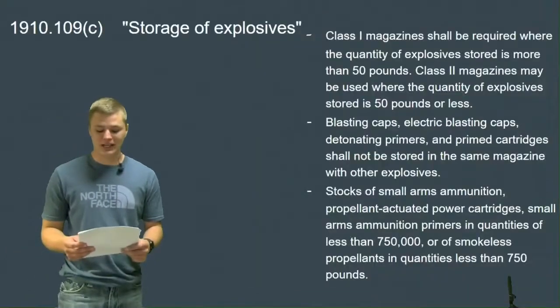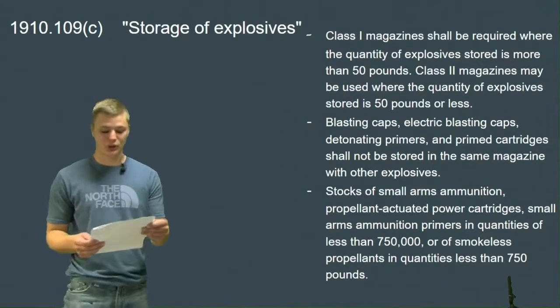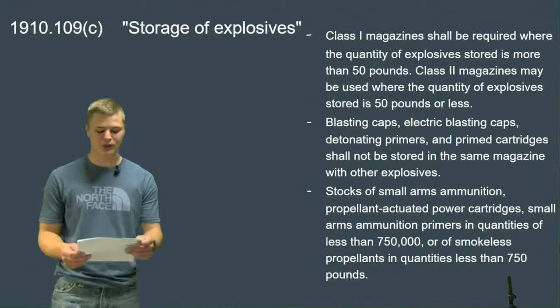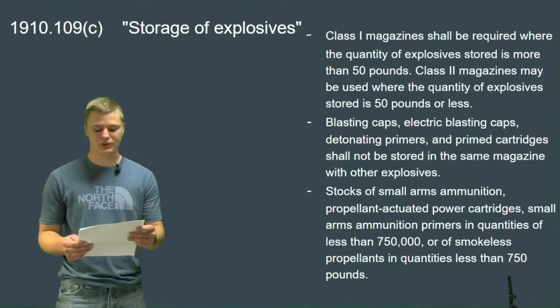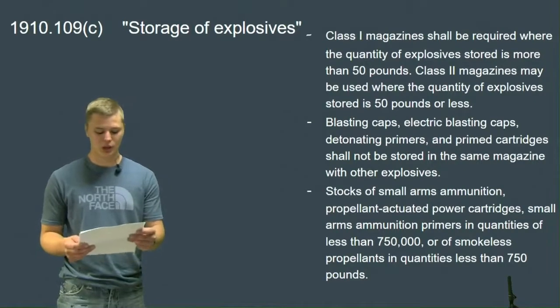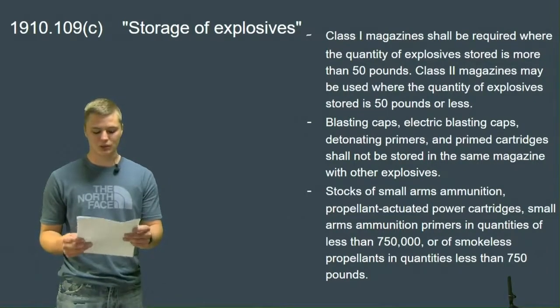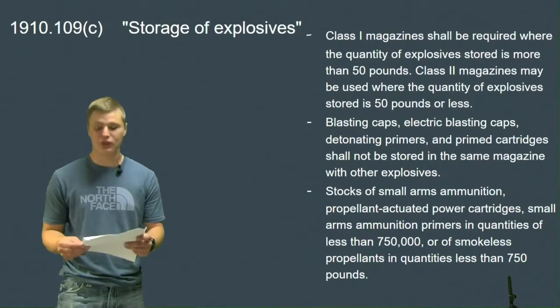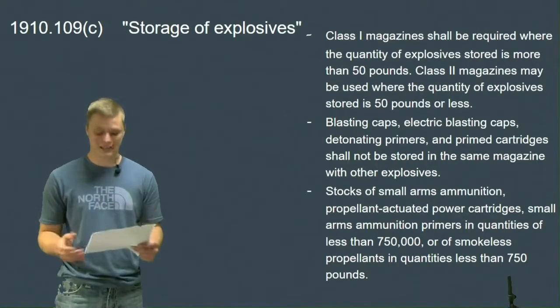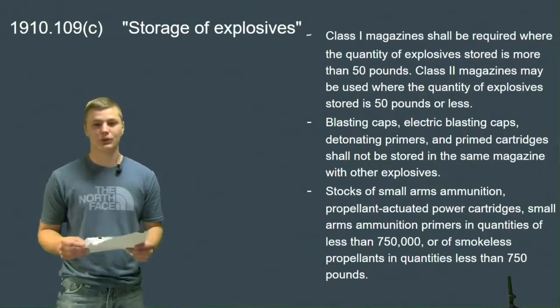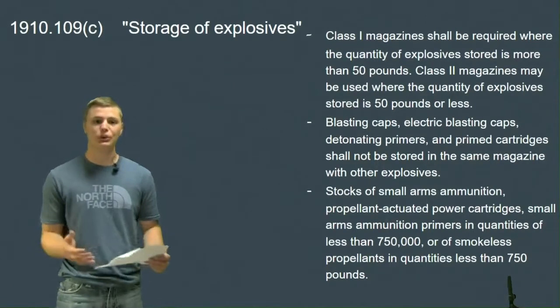Now that you know about the blasting and explosive materials you are going to be dealing with, it is very important that you know how to store them. Once again, these materials have the potential to cause harm to you and others around you if not stored correctly. Just to clarify, when I say the word magazine, it is referring to a building in which we will be storing the materials.